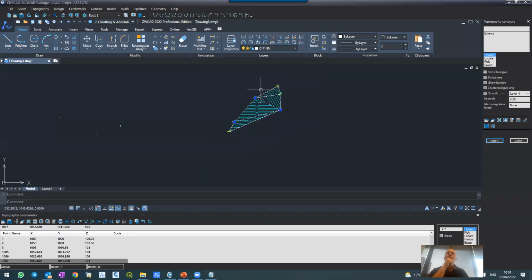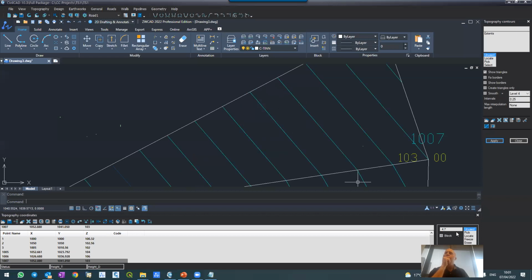The nice thing is that if now I use the same pick and click somewhere here, you see that the coordinate which I received is already in 3D because the software knew how to extract the elevation from the surface. Again, pick, click here, and I get the 3D point which sits on the surface.